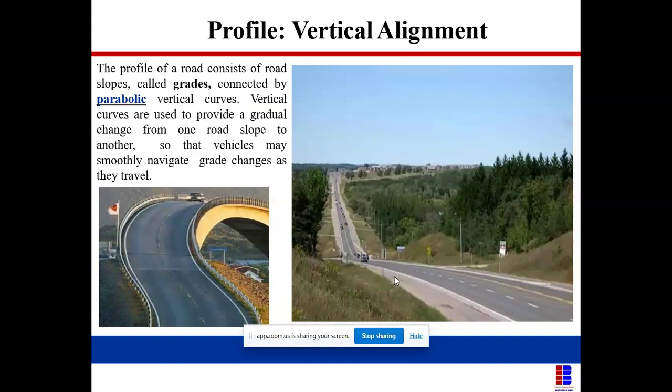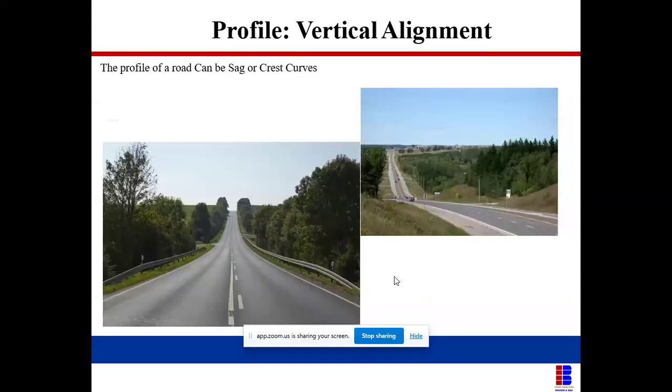But if I'm using a speed of 100 and I design a road for 60, and I'm climbing the crest curve, trying to overtake without seeing a vehicle coming from the other side, that's why you see collisions and accidents, because you have gone above the speed limit designed for that particular crest curve. And the K value there as well. So once you are overtaking using 100, and that person is using 60 to come, that person using 60 might navigate, while you trying to navigate might fall off or hit something. But that person using 60 has the leverage to dodge and avoid the collision. Those are the things we'll go through once we're using the software; you see them in practical. So these are the profiles showing the sag and the crest, that's the typical road.